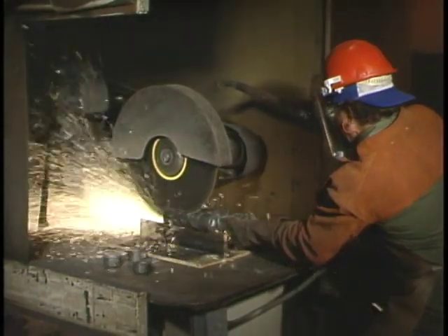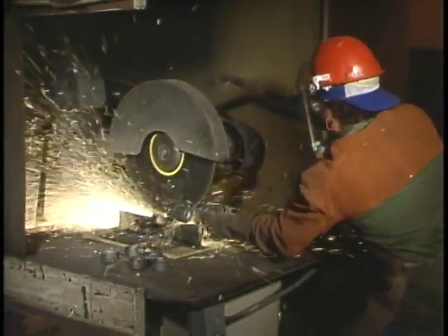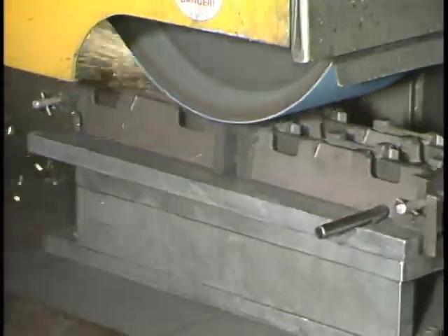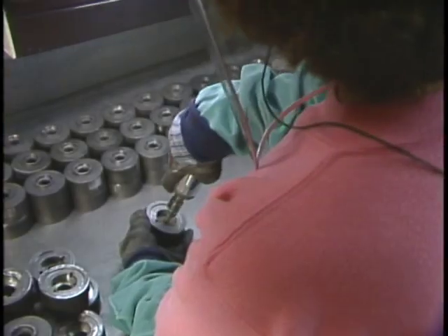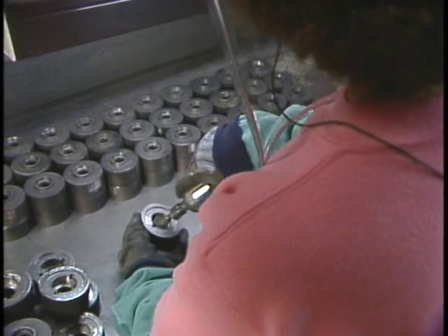The individual castings are removed from the assembly through the use of high-speed cutoff wheels and then cleaned in a salt bath. The gates are removed by grinding, and final cleaning is done on a variety of finishing machines. A minimum amount of hand finishing is required when parts are properly cast.